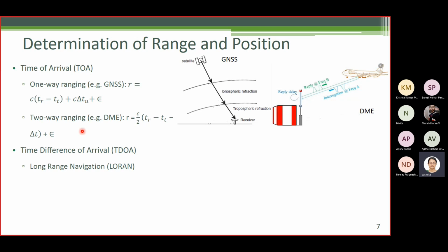So the time interval between two successive master transmissions is the group repetition interval. Each chain has a unique GRI. By processing the signals, when the aircraft or ship identifies the GRI, it will be able to know which chain it is.